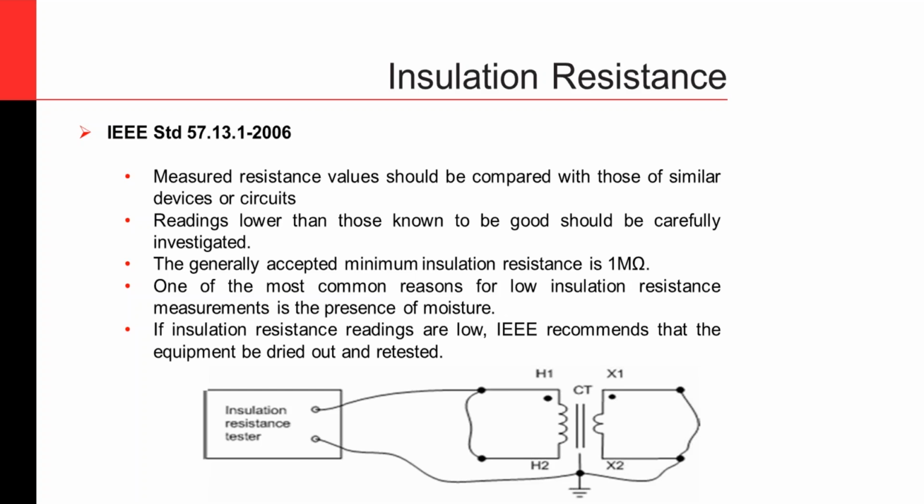If everything is isolated properly, or in other words, if everything is insulated properly, like when the secondary is insulated properly from the primary and the ground, you will not see too much of a leakage current. Your current will be very low, and your applied voltage will be higher.